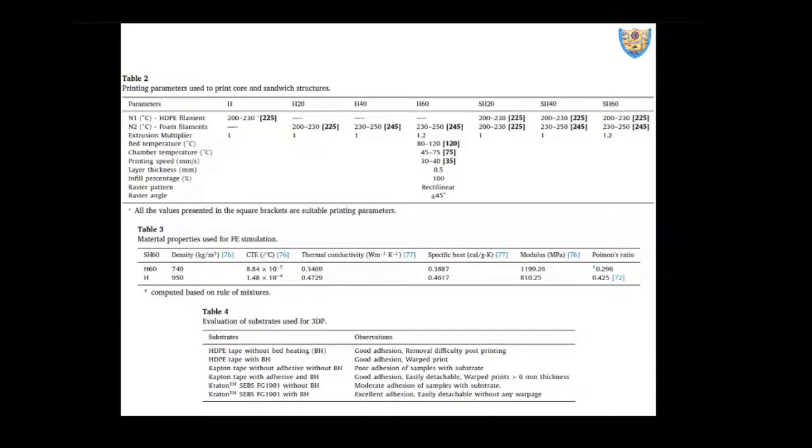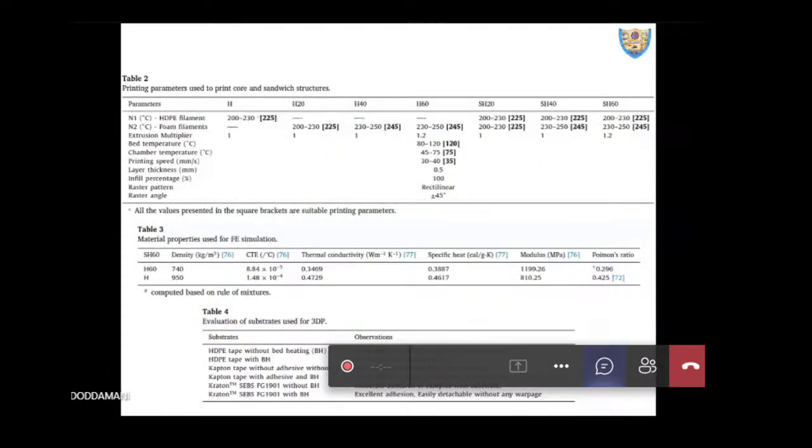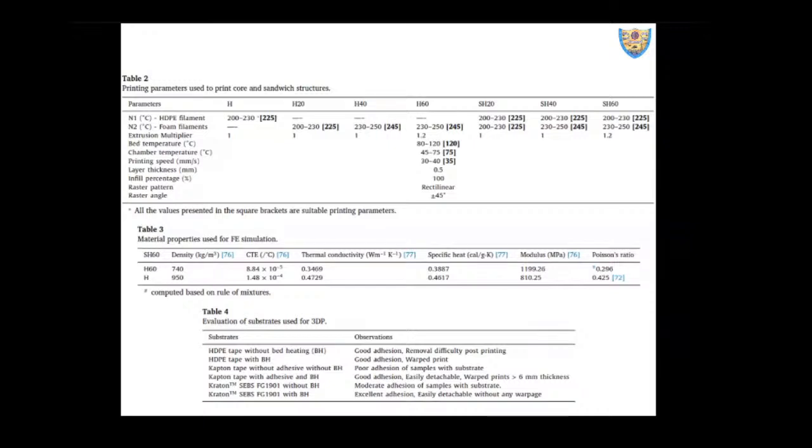So table 2 is our, I think, 3 months of work optimizing the parameters. We did not use any optimization algorithm for that matter. All was one-to-one, because here it would be a multivariate analysis. I actually wanted not to do that because I know the parameters, I know the material, I know the Tg, melting point, degradation temperature. Let me first look at that at the experimental level, because please do remember, when I say chamber temperature of 90 degrees C, we set it at 90, but there are convection and radiation losses, right? The same is with printing temperature, the same is with the bed temperature. So with all these variations, a mathematical model probably might not predict well. That's why we went one-to-one, and we rather did it on a pilot scale at an experimental level to just come up with the proper values.